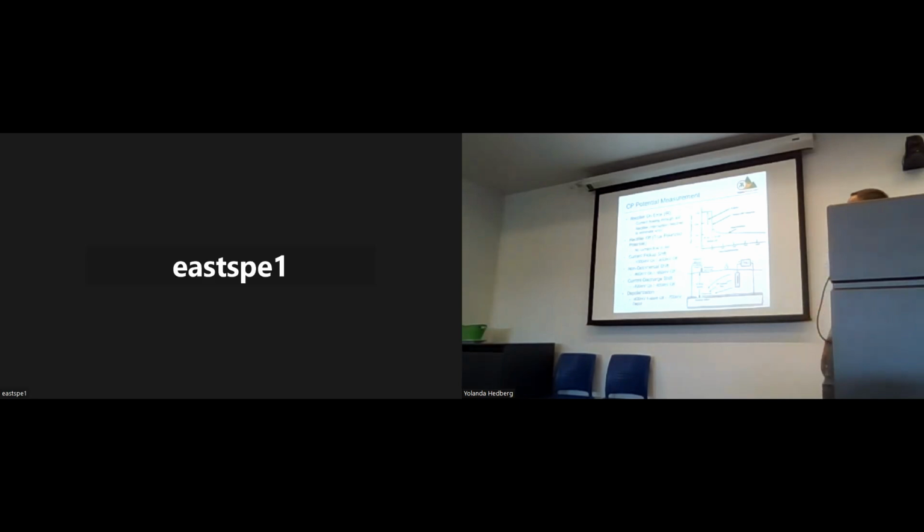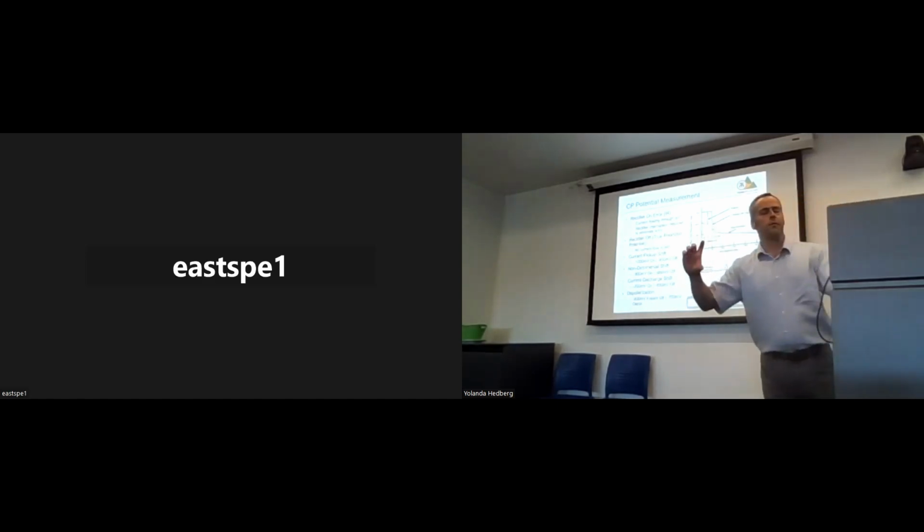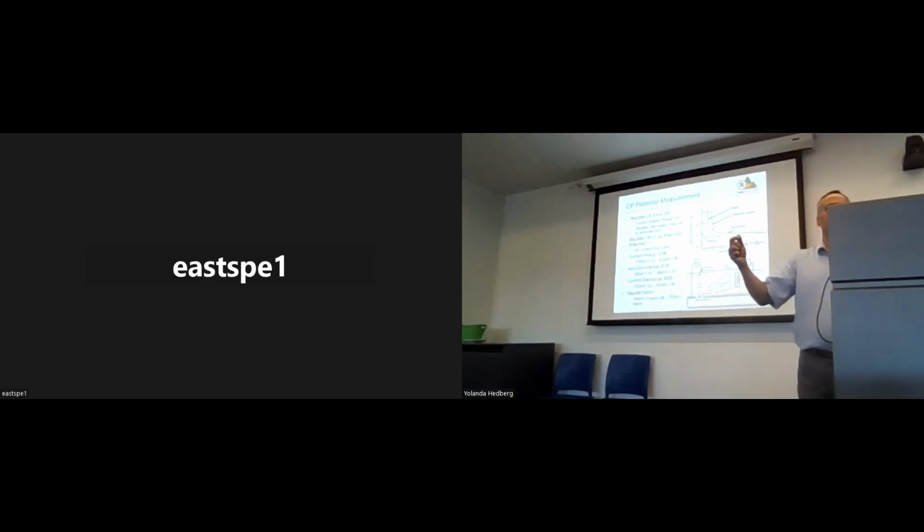Now, even though I don't meet 850, I'm at 800. What can I do? Well, I can depolarize it to see if I get 100 millivolts to achieve my 100 millivolt criterion. And that's what we did in this example.